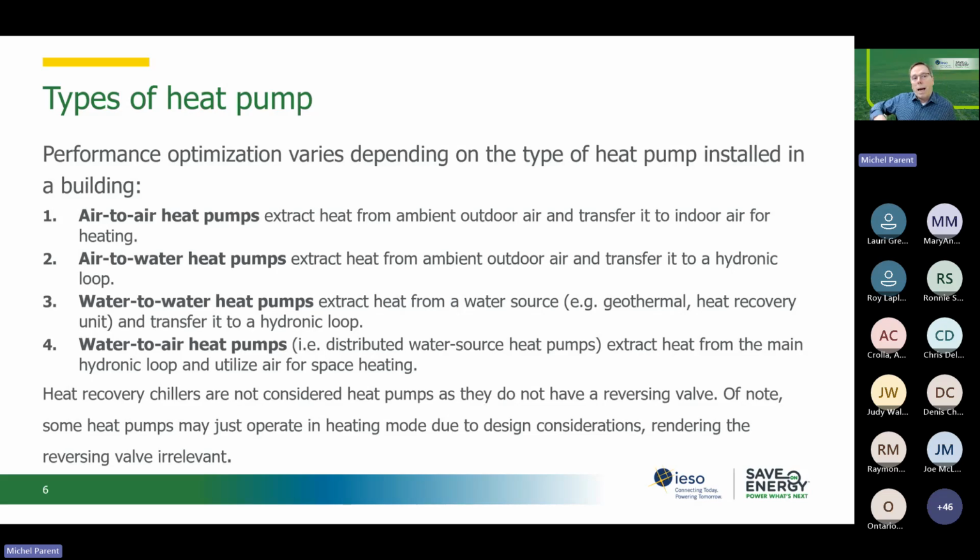And because it's also having its sink as water, so it's a hydronic heat pump, it will, as we will see, impact how you can control your supplemental heating, which is very different from what you can do when you have an air-to-air heat pump. So even though it looks very theoretical, all of those have a direct impact on how you will modify the control sequence in your BAS, because it will impact how you control based on outside air condition, as well as how you control your supplemental heating, because a lot of those heat pumps, maybe other than the geothermal one, will typically need some supplemental heat.